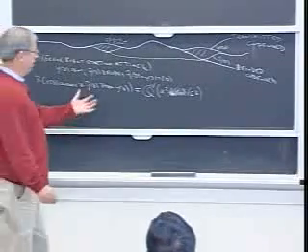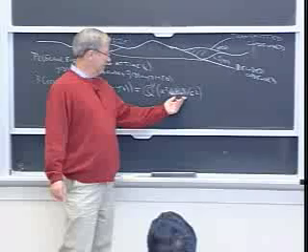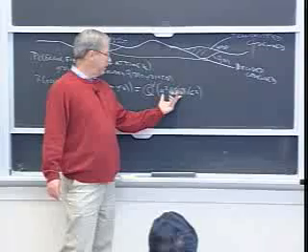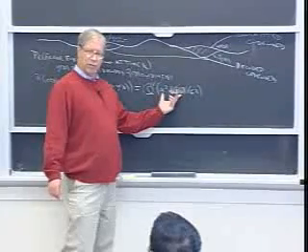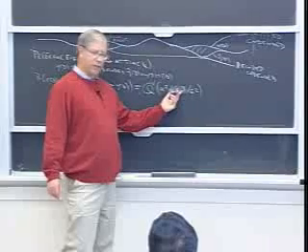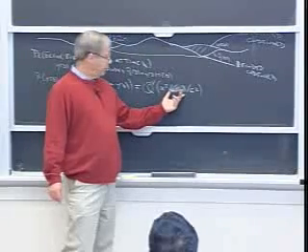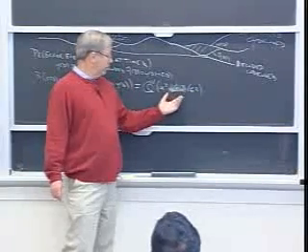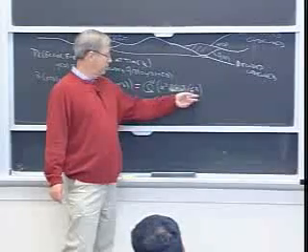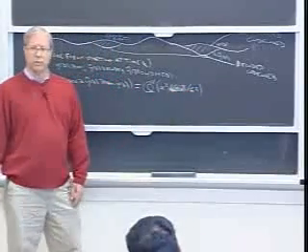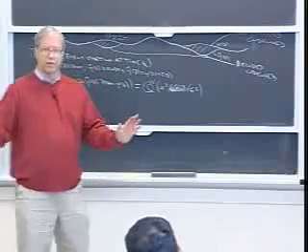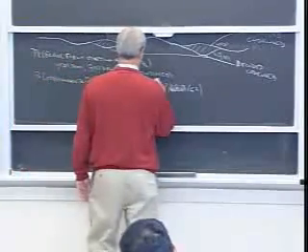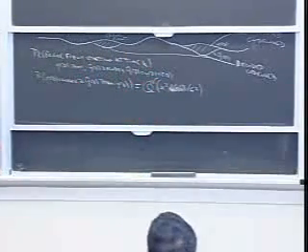So once again, we go from the Hamming weight of a possible error event to a Euclidean weight, which is 4 alpha squared times the Hamming weight. We actually take the square root of that, and we only need to make an error, a noise of half of that length, so that's where the 4 disappears. And we just get Q of the square root of d squared over sigma squared, where d is the distance to the decision boundary. Compressing a lot of steps, but it's all something you felt you knew well a few chapters ago.